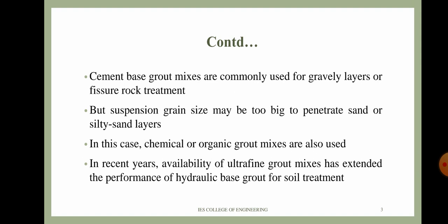Cement-based grout mixes are commonly used for gravelly layers or fissure rock treatment. But the suspension grain size particles may be too big to penetrate through the sand or silty sand layers, and in those cases, we can use chemical or organic grout mixes. But in recent years, the availability of ultra-fine grout mixes has extended the performance of hydraulic based grout for the soil treatment.